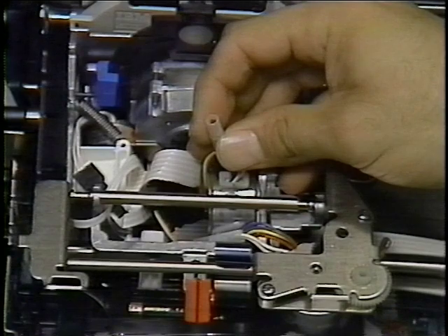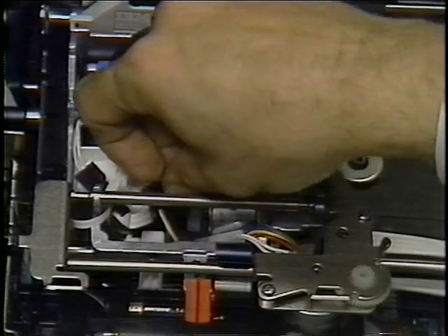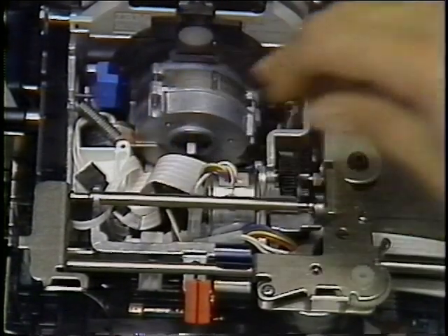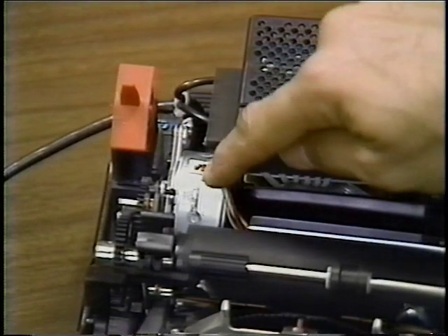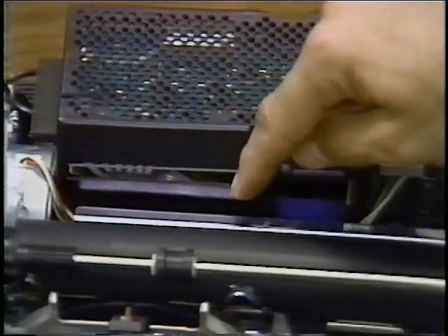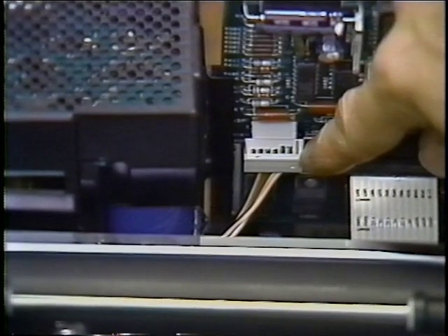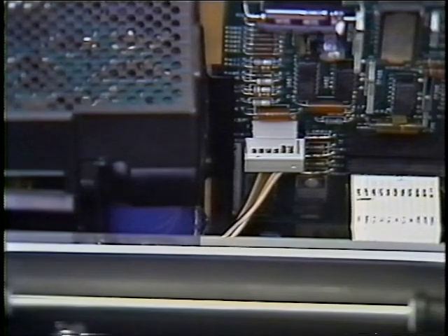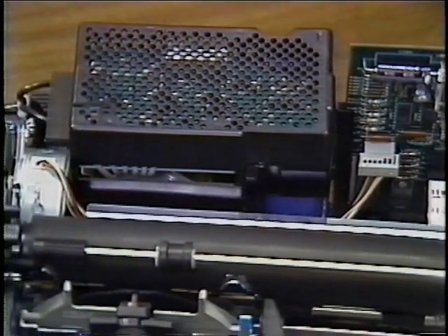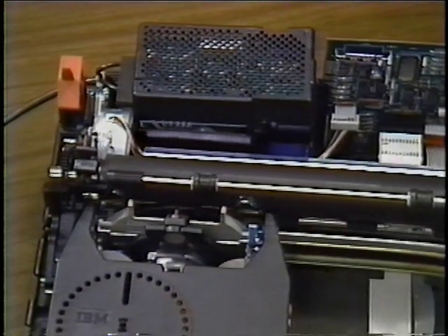Remember that both ribbon motors have their own test connectors. The resistance check for the paper feed motor is performed in the same way as the transport motor resistance check. The procedures for performing all of the motor resistance checks are in the maintenance library. This concludes the motor resistance check section.